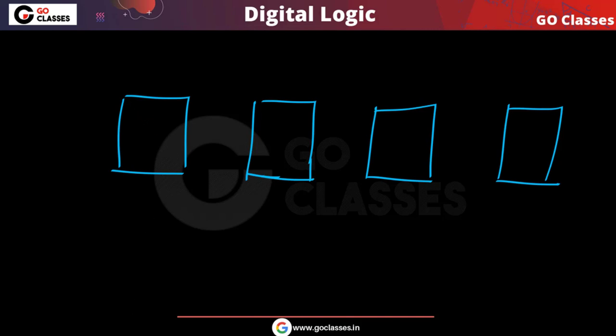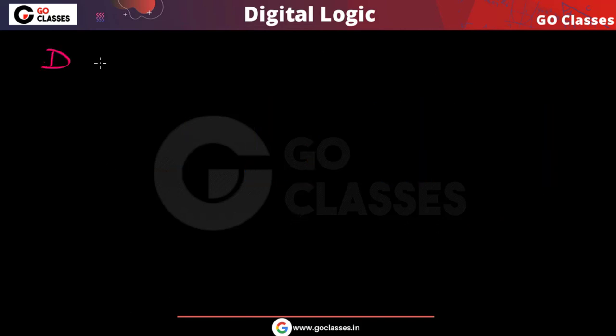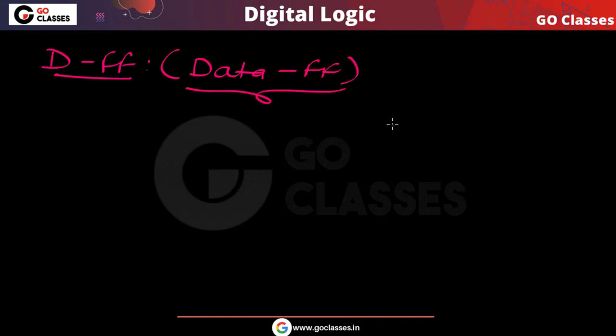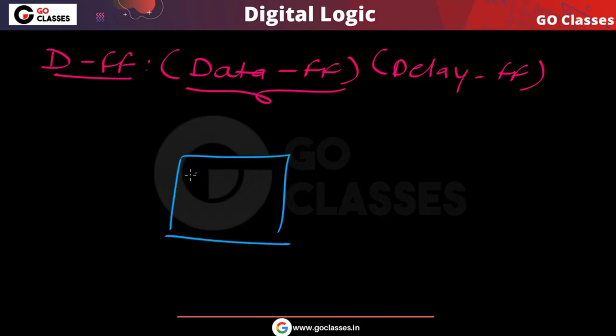Usually in registers we normally use D flip-flop, because the name itself is telling you this is a data flip-flop. The main functionality of D flip-flop is basically data storage. That is the reason this is also called data flip-flop. It is also called a delay flip-flop. We will see why. Why is this D flip-flop popular? Because in this D flip-flop, this is your D flip-flop.